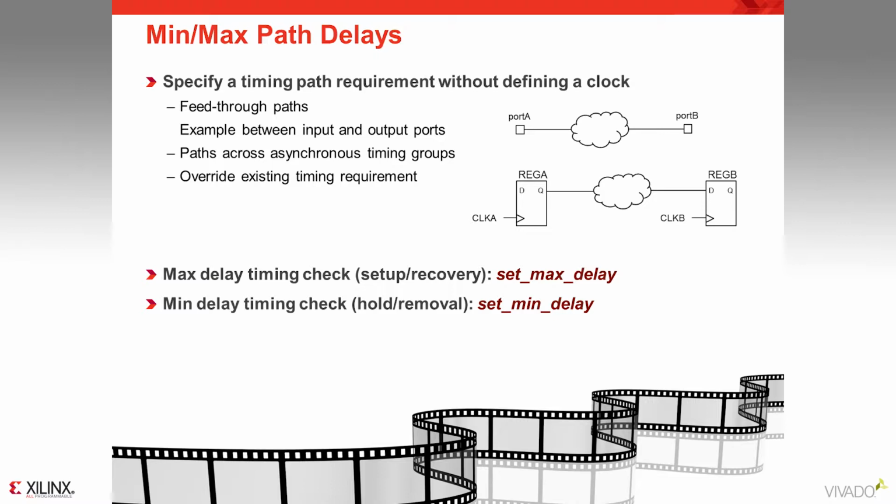The set max delay datapath only is also used to constrain paths across asynchronous paths. We will review this in the next slide. If the constraints set max delay and set min delay are applied to a path that involves sequential elements, then these constraints would override the existing timing requirements defined by a clock period.